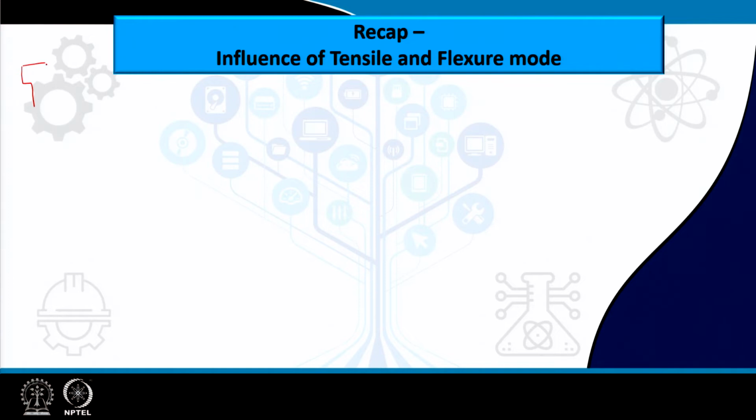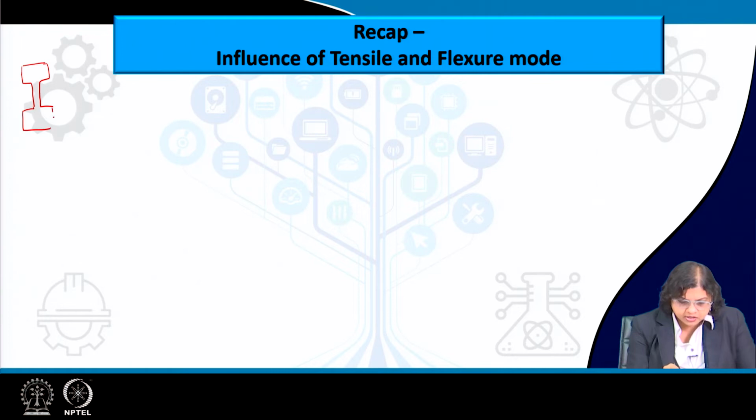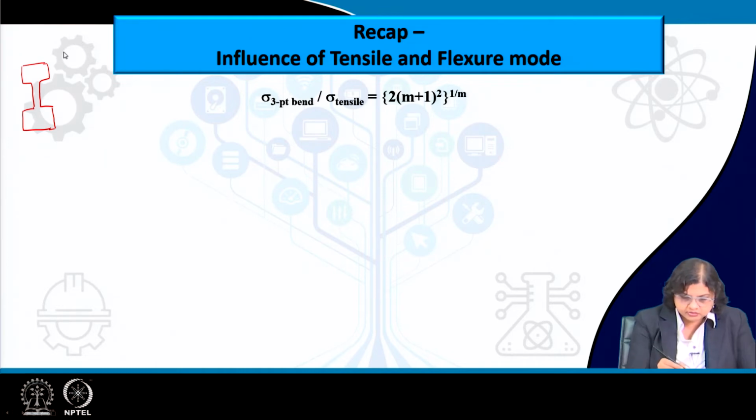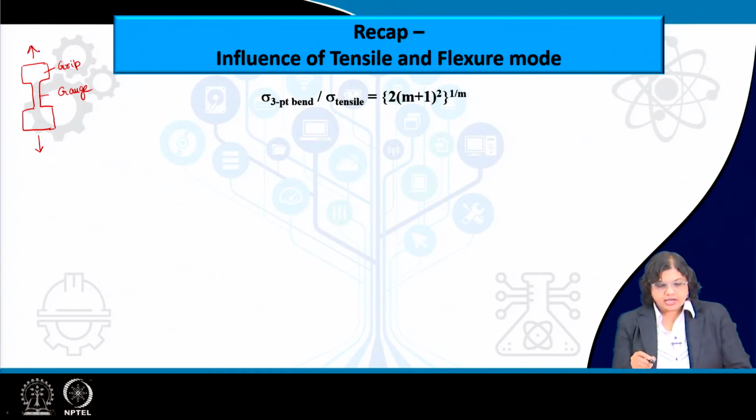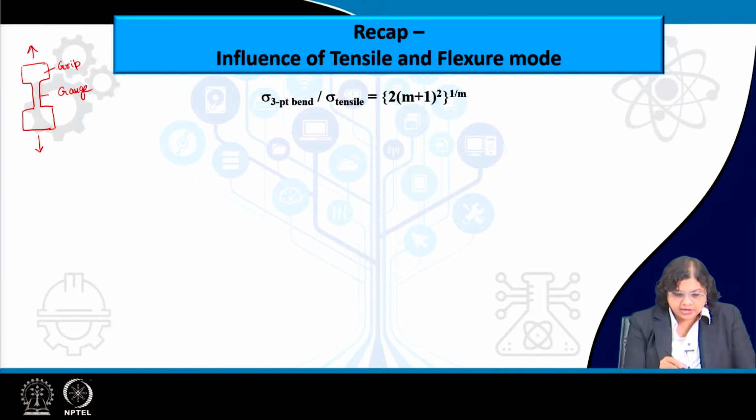And the reason for this we have specified is the condition. For example, if we have a tensile loading, this is how the tensile specimen looks like. It is known as a dog bone kind of specimen. This is the grip part and this is the gauge part. Gauge part is of actual interest because here the stress is actually acting, which leads to the deformation behavior, and whatever stress that has been applied is applicable on this entire gauge length.